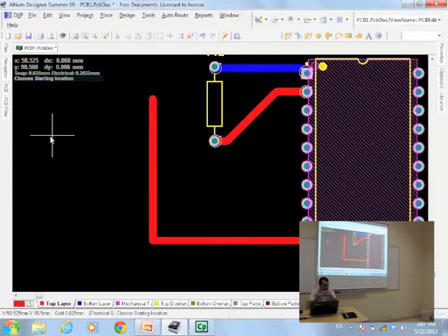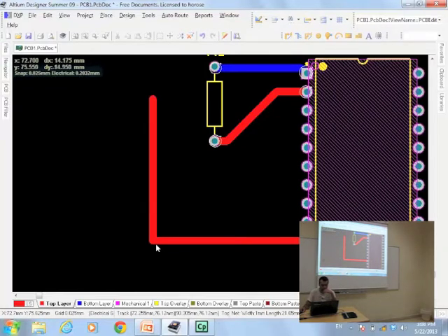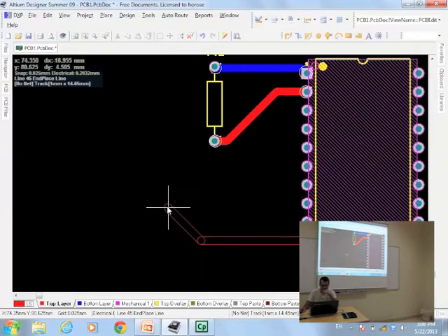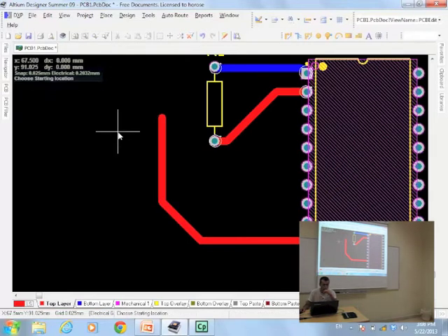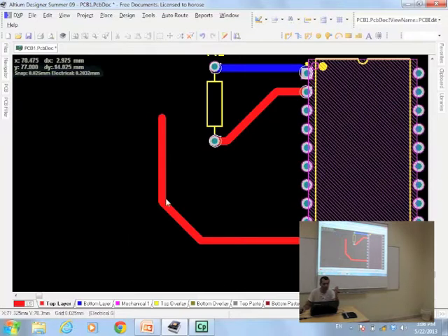That is fine. When you want to use those signals, do not use something that has a 90-degree turn. So if you want to do a 90-degree turn, do it like this with two 45 degrees of turn. Altium does it automatically for you. The 90-degree turn gives you reflection. At higher frequency, it gives you reflection and noise at the edges.